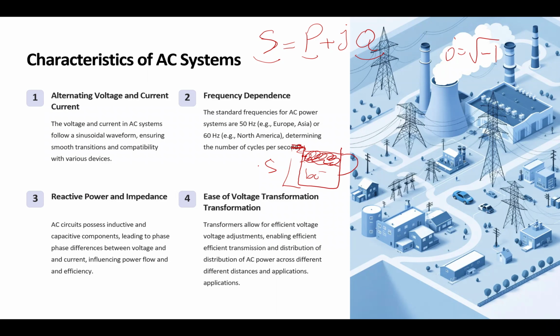It's not useful from a direct perspective, and it takes the capacity of the system. So when your reactive power is high, you have a lower capacity in your system to transfer active power. And that's why we call it a power quality issue. So we compensate, we reduce the reactive power as much as we can by compensators, so we get a better situation.